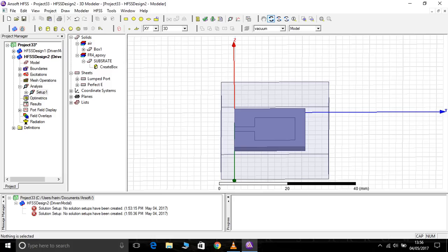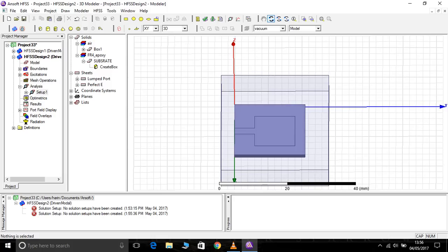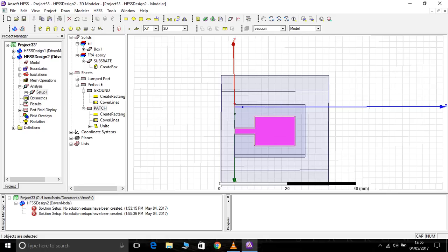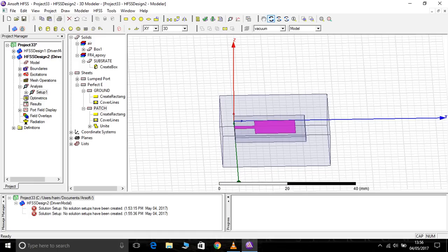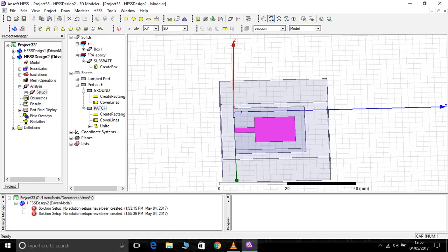And suppose you want to design a creative antenna, your patch should vary and your patch should be unique from other antennas, and that is the only thing that you have to modify in any antenna. That's all, guys. Later I'll be discussing the perfect antenna design. This is to show the basics alone, and these are not the perfect dimensions for this antenna. In a later session I'll teach you how to design an antenna using the equations for a particular frequency.